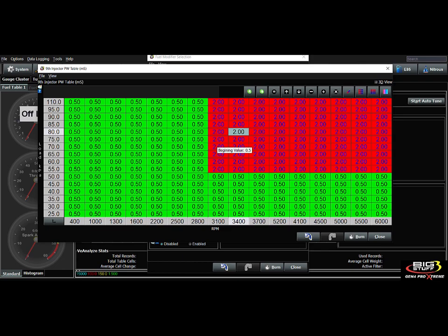And what a lot of guys do is just simply tee off from their existing fuel system and feed their fuel injectors. Now, this is a naturally aspirated setup here, but if you have a boosted combo to where above 10 pounds of boost you want to start spraying in some extra fuel. If you have a mountain motor combo, a lot of guys use this for the 16 injectors. So when it goes above a certain RPM and kPa, we start bringing in the extra fuel that way. Again, it doesn't need to be our 16 injector option where we actually kick on a second set of injectors based on duty cycle.